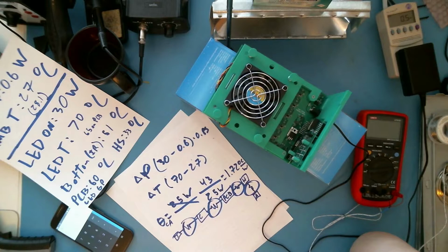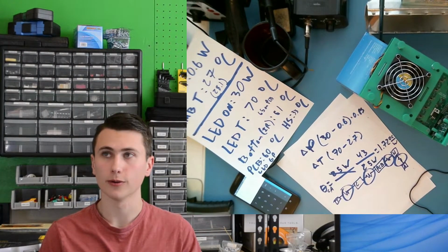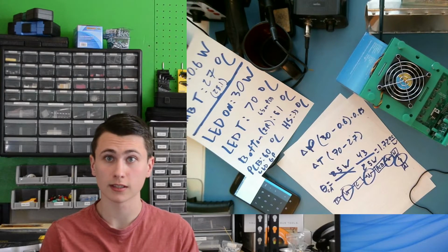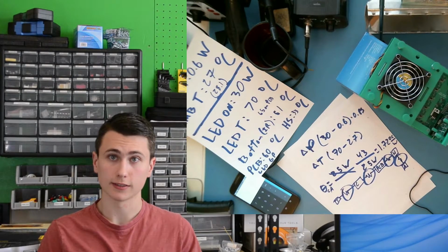The temperature measurements were correct, so the delta T number is fine, but we've allocated too many watts as being dissipated as heat. We accounted for the 85% efficiency of the AC to DC power supply, which is good. However, we forgot the efficiency of the LED driving circuit, as well as the quantity of power that got converted into photons. You know, the whole point of the project. Let's fix this math by determining the real thermal resistance.